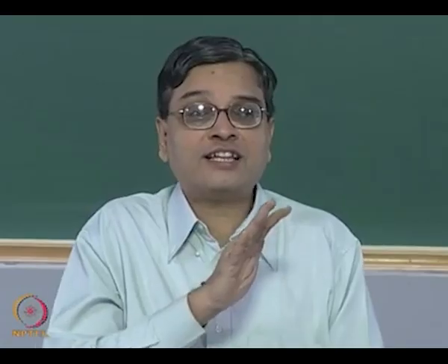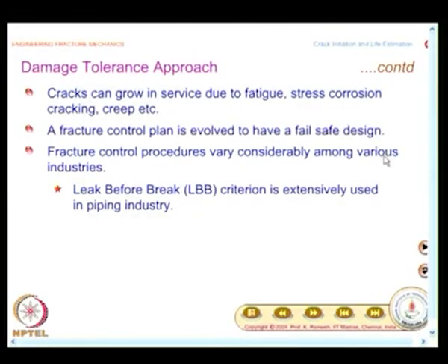See, earlier you had concepts like infinite life. People have understood there is nothing like an infinite life. What we want is, if a component is going to fail, let it fail safely. So, that is the best that you can get out of it, and that is what damage tolerance is all about. And how do you do fracture control? They vary considerably among various industries. If you look at nuclear installations, the leak before break criterion is extensively used in the nuclear industry, where you have heat exchangers. You can also extend it to the piping industry, where you have chemical processing plants and so on and so forth.